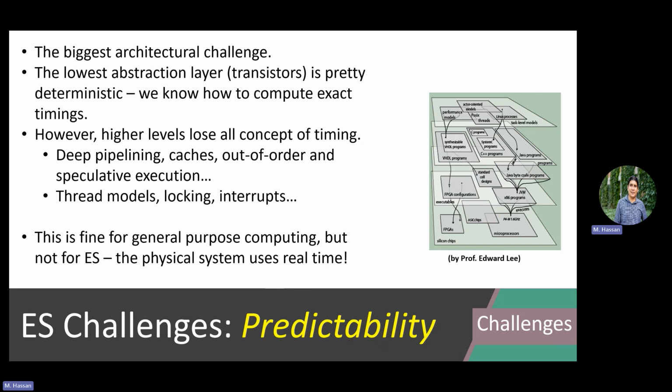So now, how do we ensure timing? This is why we call them real-time systems. How do we ensure timing? Through something called predictability, right? You want to ensure that your system is predictable. Why predictable? Because predictable means its behavior is known from a timing angle under all possible scenarios, right? Under all worst case scenarios that can happen in the environment. For example, I will never exceed my deadline. Good.